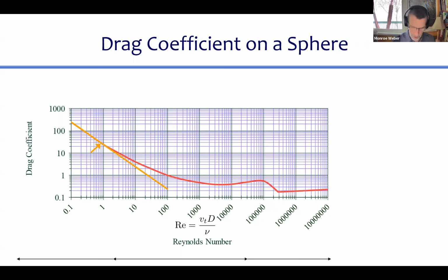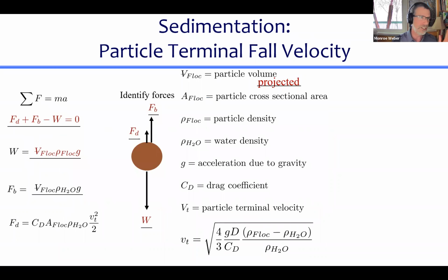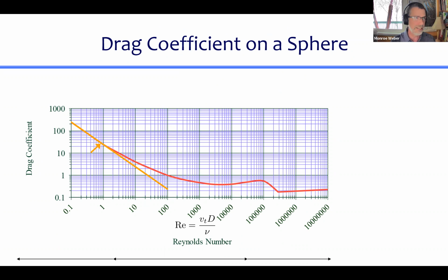And then here's the next part, and that is this drag coefficient is like the big unknown, and that's what's needed to solve this equation. The drag coefficient, unfortunately, is not a constant. It's a function of the Reynolds number, and it's a complete mess. And I would love it if you would see that this graph is so similar to one other big graph that I showed you in this course. Anybody remember which one? This graph is a lot like, who wants to be brave?